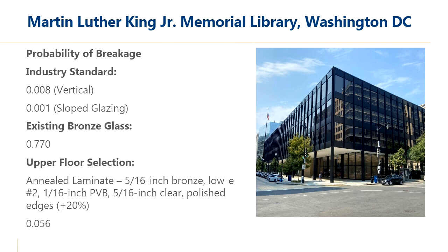And polishing the annealed glass edges, which is typically assumed to increase the strength of the glass by 20%, brought it further down to 0.056. Though that doesn't meet the industry standard probability, based on the fact that cracking in the glass would not result in the glass falling from the opening, thanks to the laminate, and the fact that most past breakage was attributed to corrosion of the glazing pocket or vandalism, we were comfortable with that breakage probability trade-off. And just a quick note that no breakage has occurred since it was installed in 2020, and we would expect to see that breakage by now if thermal stress was going to be a concern.